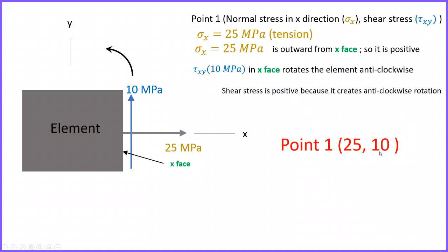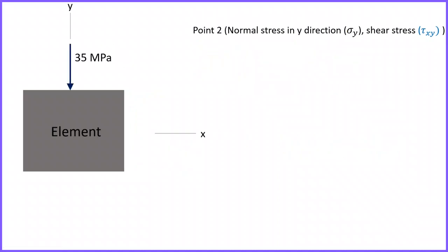And 10 megapascal is the shear stress on the x face, and it rotates this element anti-clockwise, and according to the sign convention it is positive.